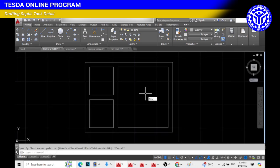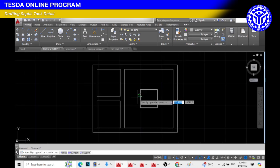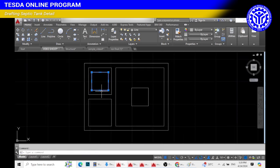Using the Rectangle command, create a manhole. Set the dimension at 0.4 by 0.4. Using the CO command, copy the manhole on the other 2 chambers.